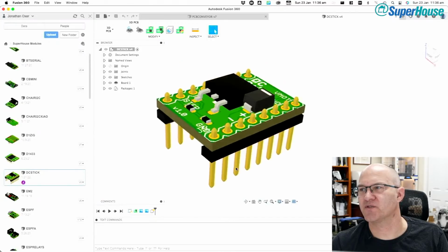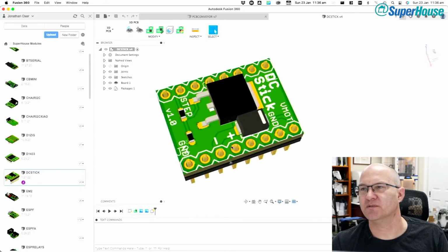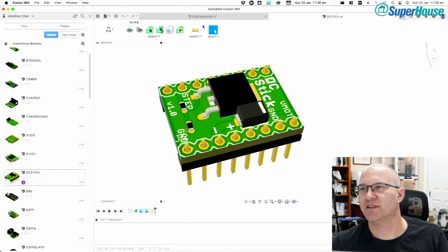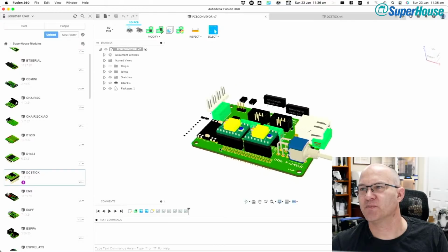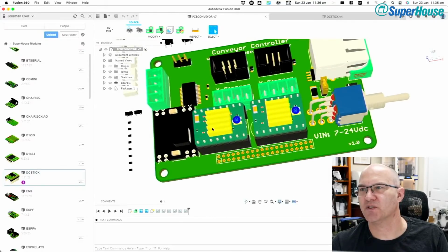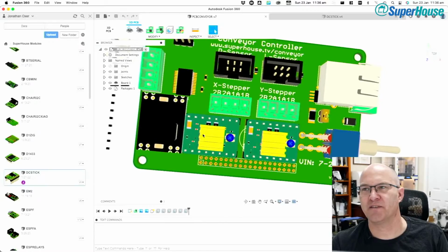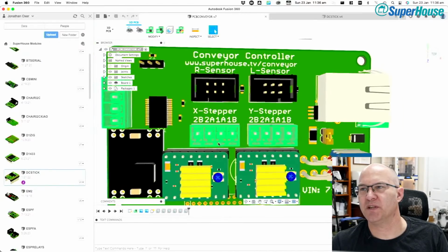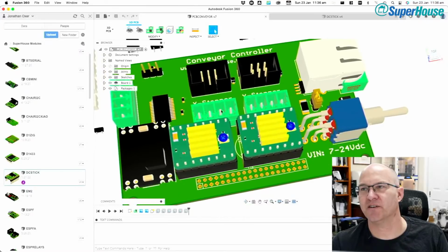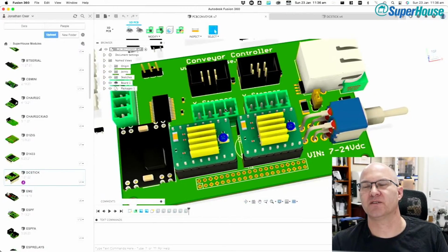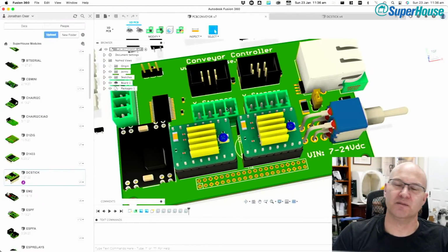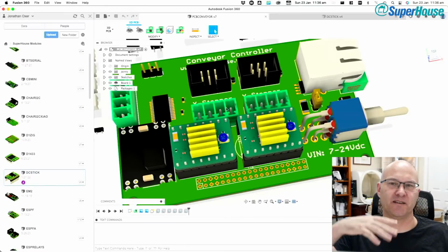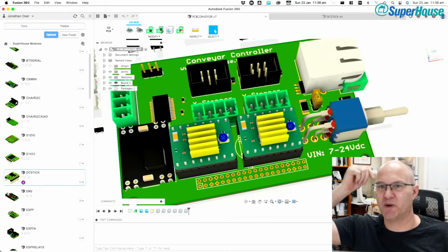So what you can do is drop this module onto this board in place of a stepper controller, and now instead of having a stepper connected, you would use the 1A and 1B pins, and you could fire a high current solenoid, or it could be a DC motor, or it could be a relay, or it could be a pneumatic actuator, for example.